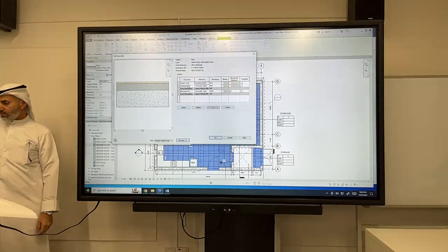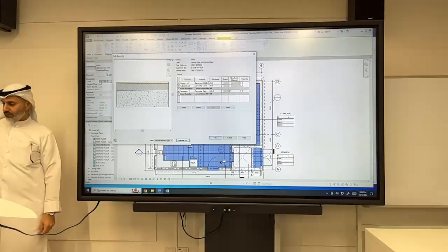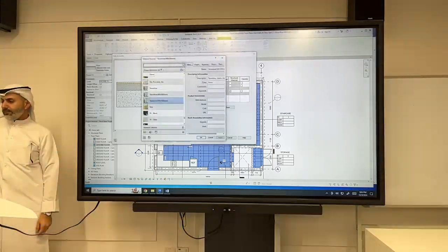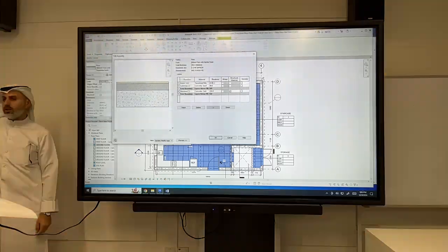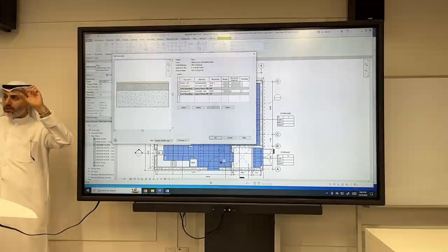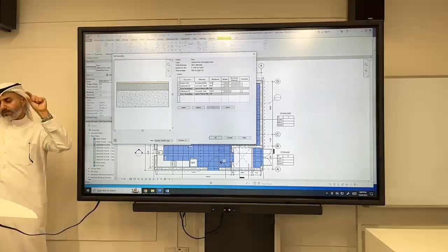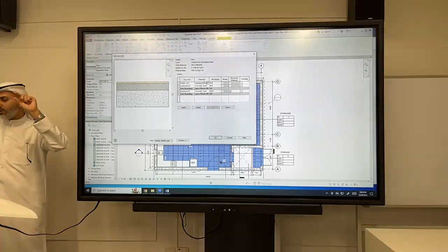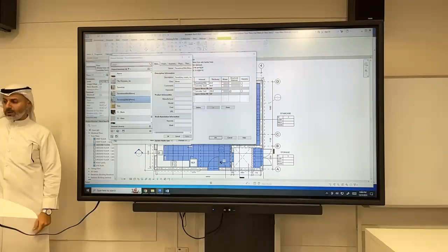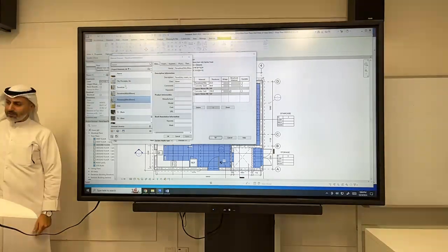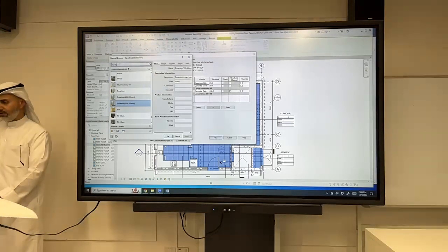So go to travertine 500 500. Edit, here, the material. Generally, thicknesses, you'll see here, thickness 20 is okay for natural stone, which is 2 cm. So you don't have to change that. We just want to change the material. So click on this, now travertine 500 500. You can select a different material from here, or you can do search. So I'm doing marble.